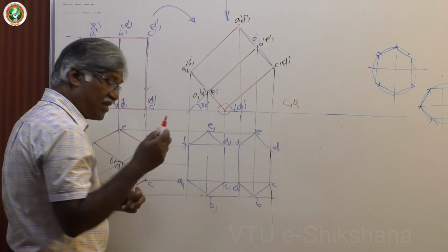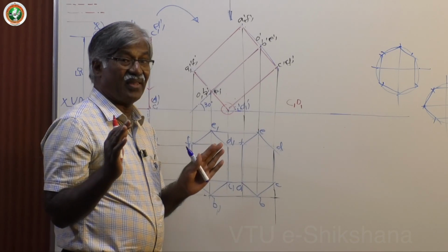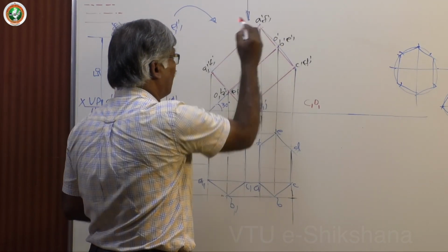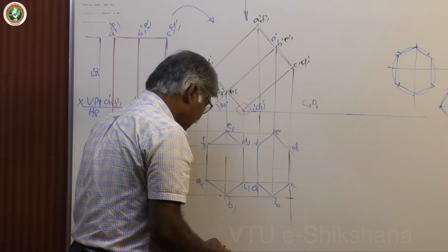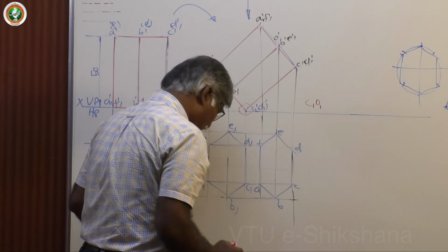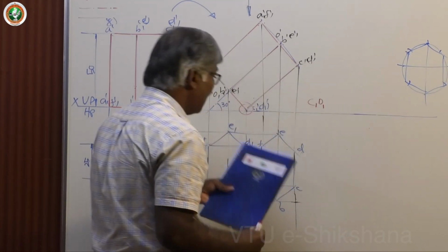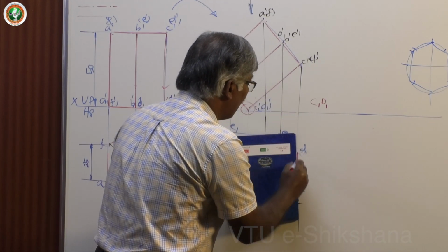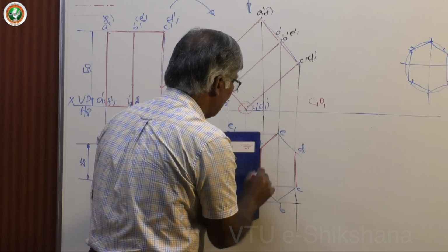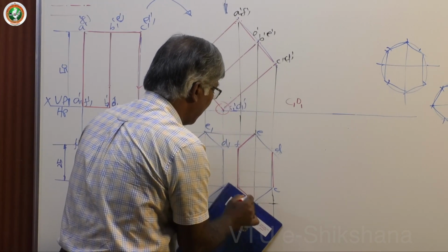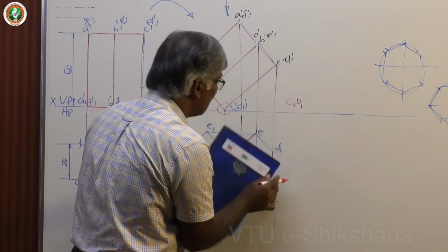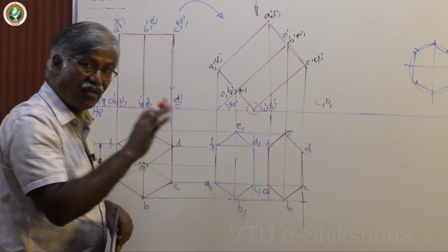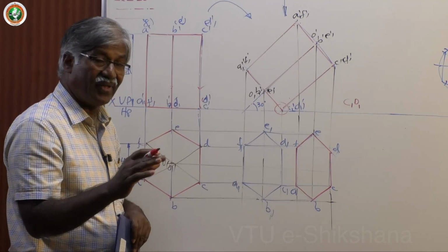Now let us start from the visible key surface method. The nearest key surface is visible, that is top face is visible. First dark it. Dark top face edges. It's very clear cut and narrow method, no confusion. Especially more the number of edges, you have the problem with the farthest item concept. So this is very easy. Okay. First dark all lines of the visible key surface.